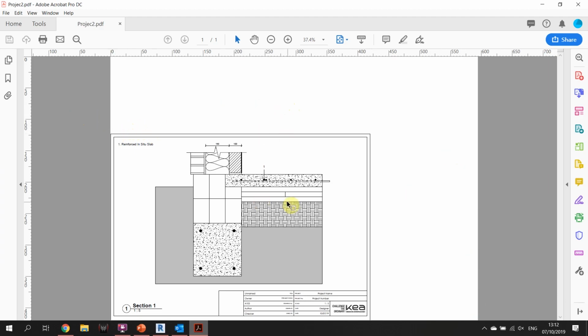If you would click fit to page, it would still be on the full size of the paper, but if you would print it out, it would not be in a scale 1 to 5. And that's what we aim for. We want the proper scale because it's a 2D drawing, a constructional or architectural drawing. It needs to be in a proper scale, so that's important. Make sure to get all of those settings right.